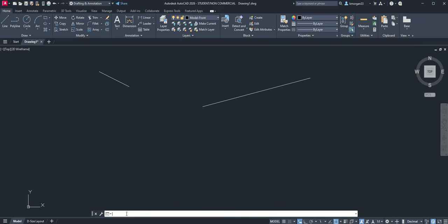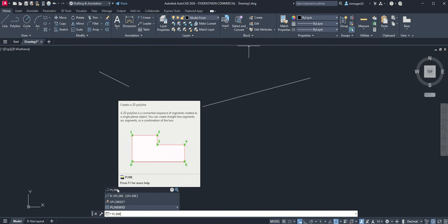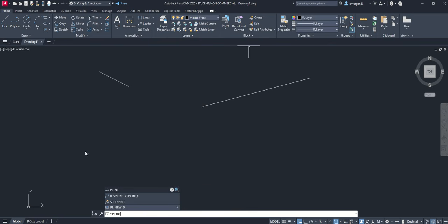The command for polyline, you type in PLINE, and it's going to show you the same thing that you see right over there, enter home tab. You can draw easily, like a rectangle with a little inverted L shape right there for you. Then you can draw like that. So let's just start with the clickable one with the polyline, and we click in, and now we are in PLINE mode. If you start to click, it will go.